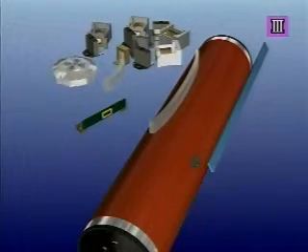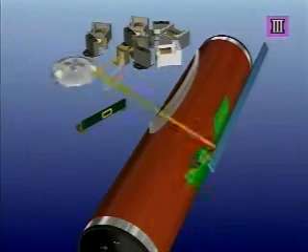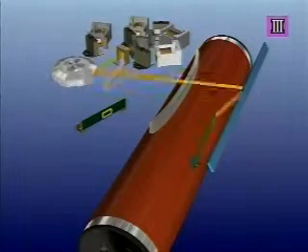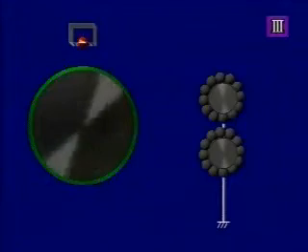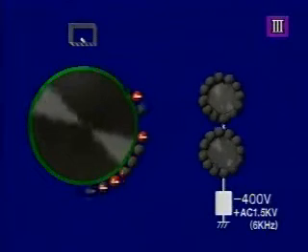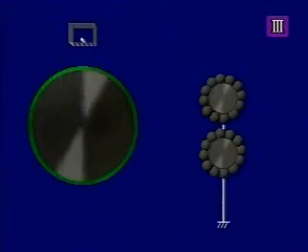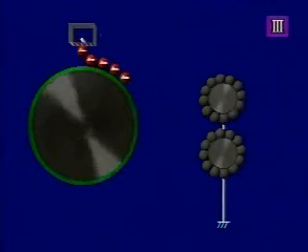Since this method is beneficial for laser exposure scanning and provides longer life for the laser diode, it is used for most of the digital copiers. Since the drum and developer are driven separately, the magnetic roller and developer bias are turned off before the charging output is turned on, to prevent the unwanted toner from adhering to the drum.